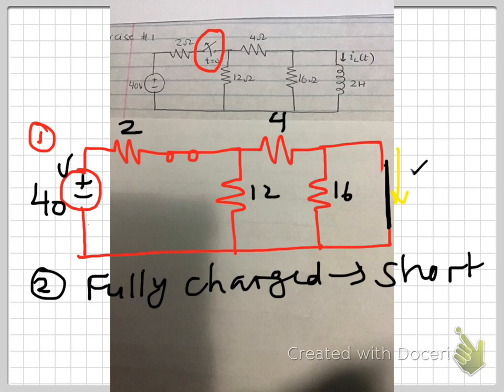So let's say this is the current flowing through this branch, and that current is considered as IL0 minus. So let's calculate that current. You can use any methods: current division, voltage division, Ohm's law, KVL and KCL. So calculate IL0 minus. Okay, let's look at a bit of analysis in here. The 16 ohms is in parallel to the short circuit in a pure parallel combination.